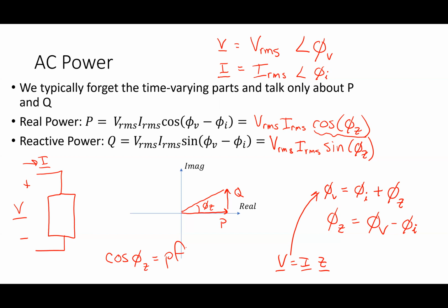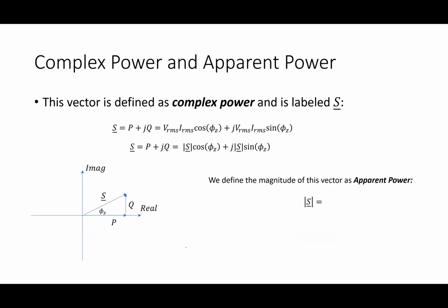Yeah, Rachel. If they ask whether the power factor is leading or lagging, are we determining that based on the voltage or...? We're determining that based on whatever we're given. Usually it's based on the impedance. It's based on whether it's an inductive load or a capacitive load. We're actually going to do an example on that in a little bit. Good question.